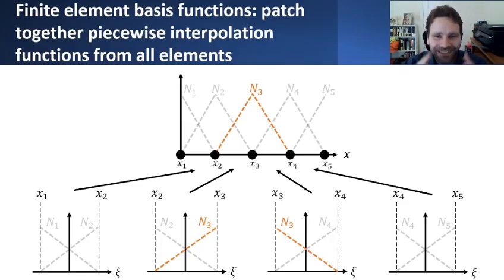The idea here is that I can come up with some local basis function defined over the full structure itself, one for every node, and in particular, for node 3 in this example, the resulting basis function will look like this local kind of hat, but it will be defined in such a way that this resulting basis function n3 associated with node 3 will have a value of 1 exactly at x3, and it'll have a 0 value at nodes x2 and x4, and in fact, it'll have 0 value anywhere that's not in the elements directly connected to node 3.